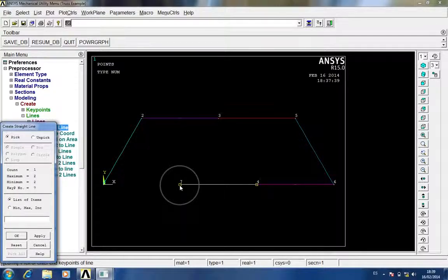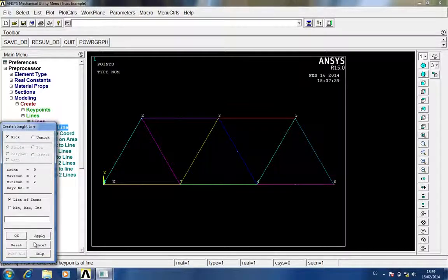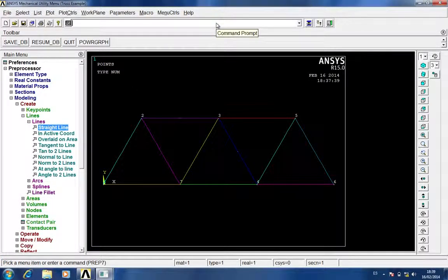Here it doesn't really matter which element we unite first, as Ansys is going to give each bar one number. If I defined them in another order, it doesn't matter. I can check in Ansys which bar is which element and then compare it to my handmade results. So now we have finished with the lines.